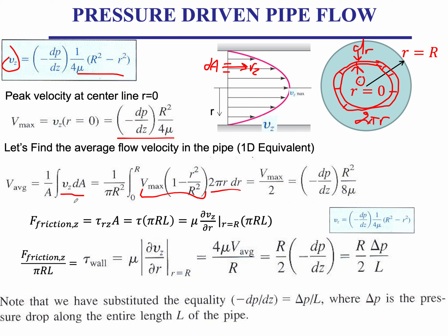You plug it in there. So that gives you the volumetric flow rate, the Q, and you divide the Q by the A, you get the average velocity. And if you multiply the Q by the density, you get the mass flow rate. So now this is very familiar to us. And here we get this, your average velocity, and it's related to the pressure gradient, the dimension of the pipe, as well as the viscosity. So if I multiply my average velocity by the area of the pipe and the density of the fluid, I get the mass flow rate.